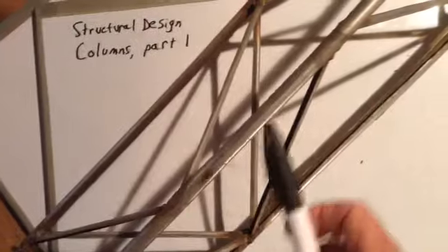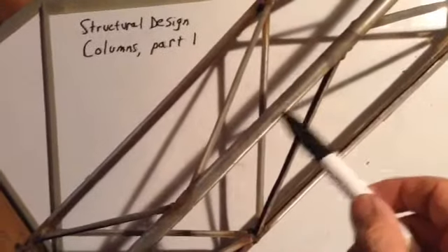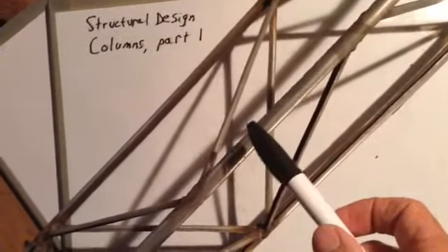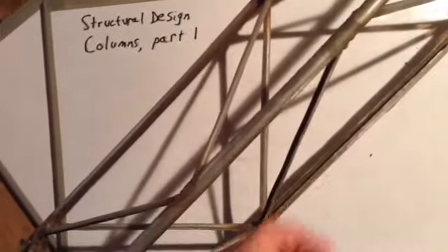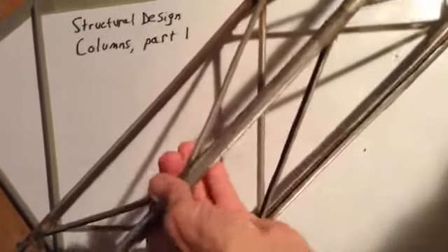But each segment on this truss here, each segment that's in compression, can be considered a column. This is a 10-foot long tail boom mock-up. See, there's one end of it where the tail of the airplane goes on. Here's the other end. It's a 3-flanged truss. It has a top flange that's in tension and 2 bottom ones that are in compression. What we're going to look at is this particular one right here.